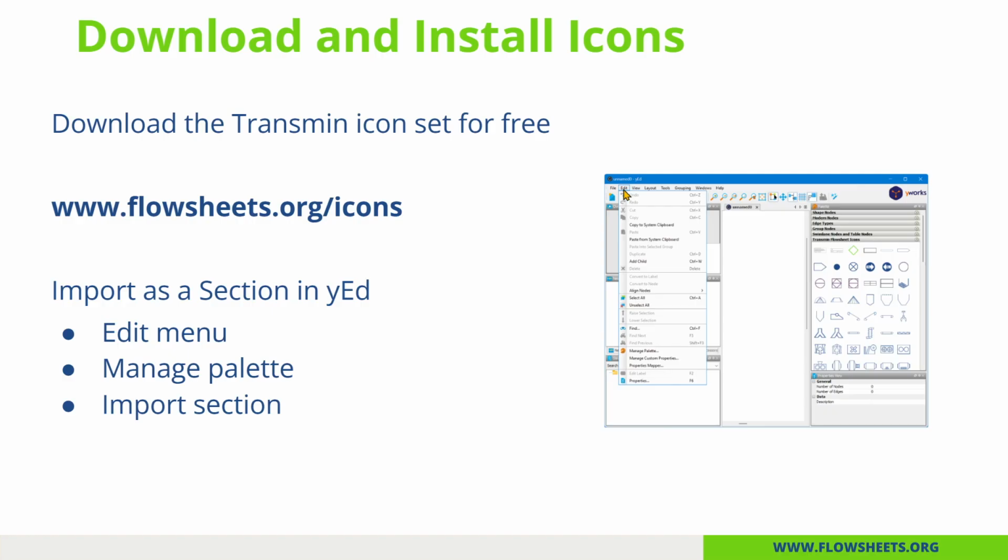And then you would want to go to flowsheets.org, which is a non-commercial website that we've put together to help promote flow sheets in the mineral processing industry. And there you can find icons and stream palettes for yEd for download. So you just have to download those and then go to the edit menu in yEd. And then at the bottom here, there's the manage palette. And then you can import those palettes into yEd.